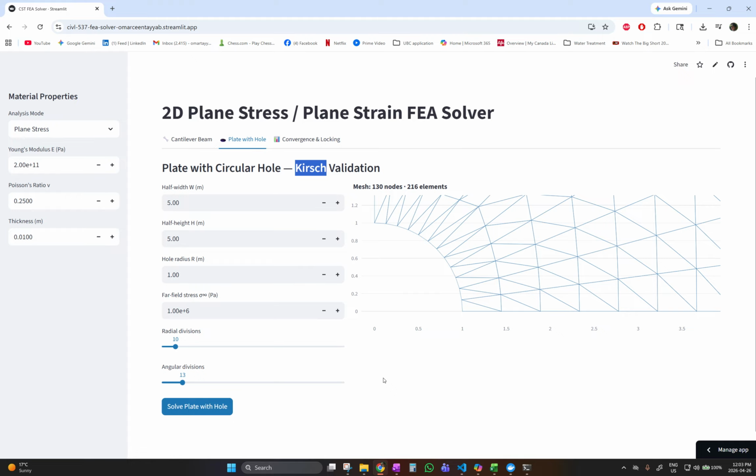To simulate that, translating that into geometry, what we're trying to say is that the radius of the hole should be negligible compared to the total width of the specimen, right? But that would mean that our smallest element needs to be at least half as small as the radius of the hole, which demands an immense computational requirement.